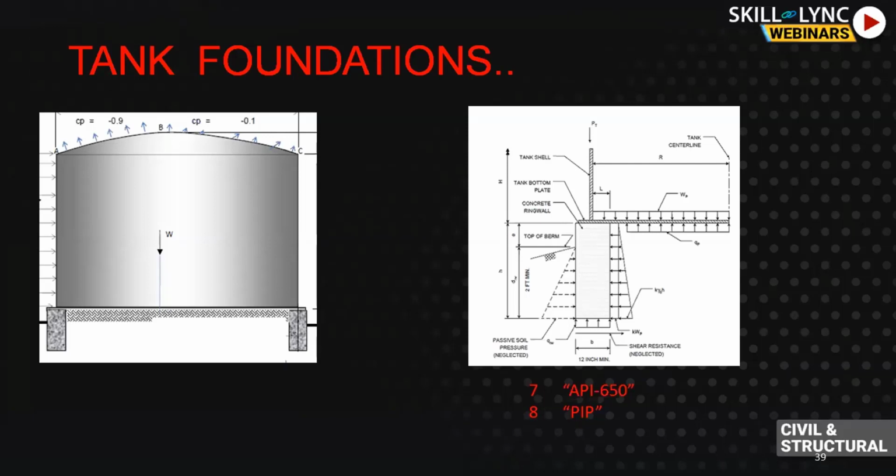So other than the analysis and design, when we are designing a ring foundation or a raft foundation, first we will need the vendor directions, inputs or requirements. How much will he make the shell sit on the ring foundation? How much should be the top of the berm? What is the minimum size of foundation we need from the geotechnical report? What should be the minimum width of the berm? The minimum width of your ring foundation? What should be the minimum embedment of the foundation? So serviceability criteria will again govern all of your tank foundation. This is how we proceed in tank foundation.